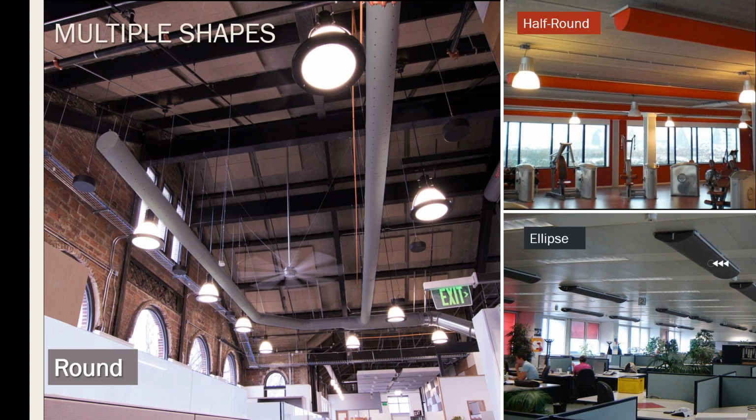This can also be done with the ellipse shape. The ellipse shape is available for draft-free air distribution and lower ceiling applications like classrooms and offices. And that's what's going on in this picture, bottom right-hand corner. They've replaced the metal diffusers that they had in there with these fabric diffusers for more comfort in that space.